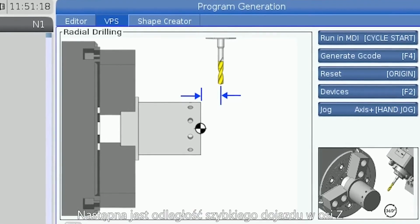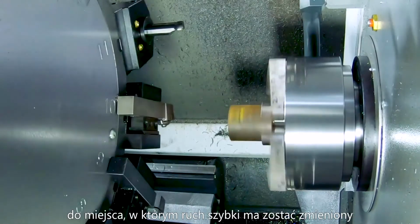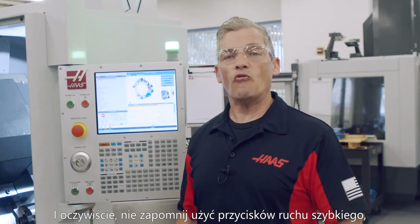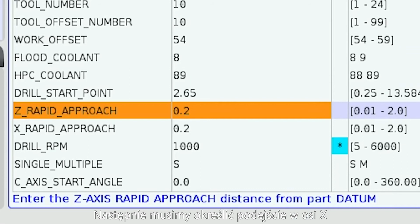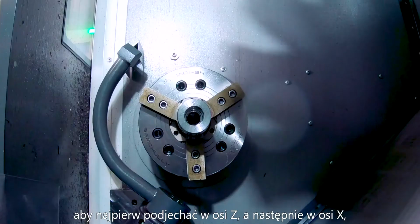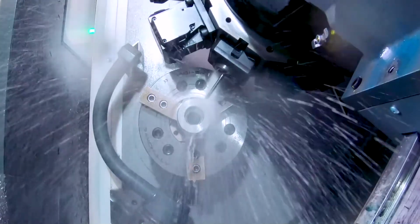Next is the rapid approach distance in Z-axis. This determines the distance from the part face to where the tool will switch from rapid motion to feed motion. This value defaults to 0.2 inches, and I'll leave it set to 0.2. And of course, don't forget to use the rapid override buttons to slow things down when you run the part for the first time. Next, we set the approach distance for the X-axis. Again, I'll leave this set to the default 0.2 value. When rapid approaching the part, it is usually safer to do so along the Z-axis first and then the X-axis to make sure you have enough clearance moving forward towards the chuck.